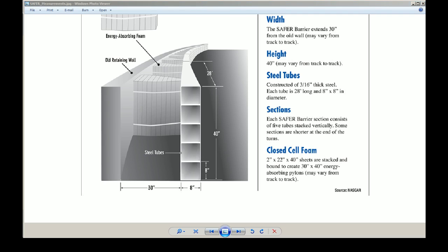And it should be 0.20 meters thick for the wall, for the steel wall. That's the closest measurement to 8 inches that you can get. Yes. 0.21 is actually 8¼ inch, so it's a little bit too big. 0.20 is the measurement that you'll use for the width in meters in Sandbox, and 1.02 is the height of that steel wall.